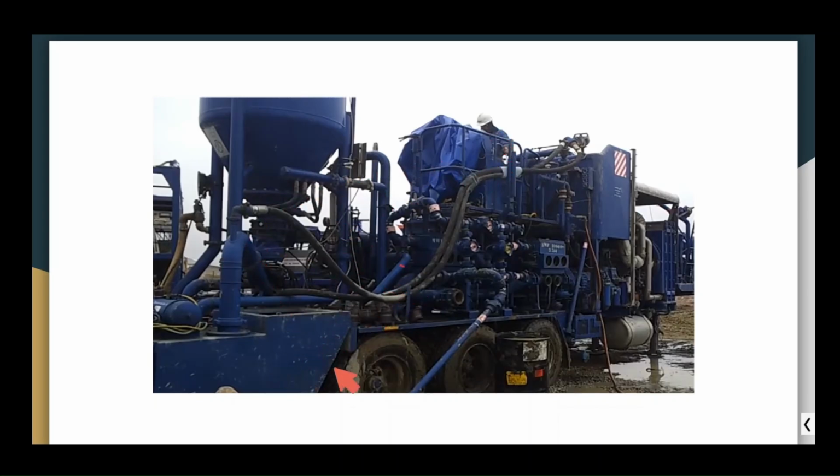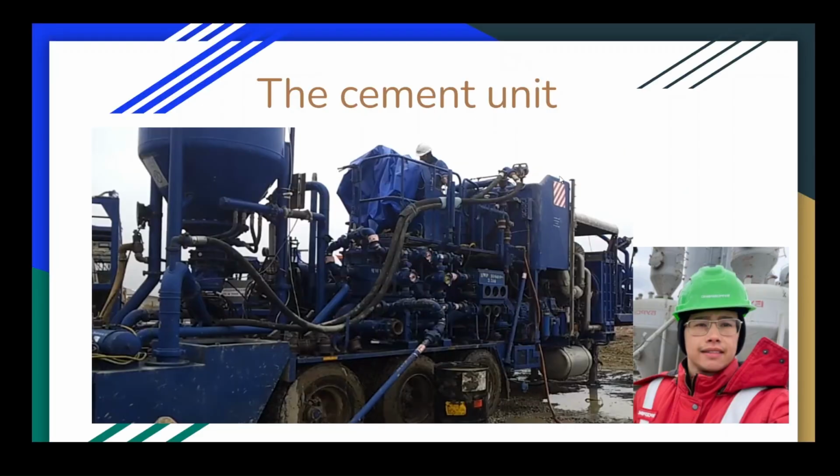The whole pipeline is covered by this mixer, so we can't see the whole process, but I tell you, I did it. So we prepared our cement slurry to the right density level, so we can feed our high pressure pumps and flow by high pressure lines over here to the well.